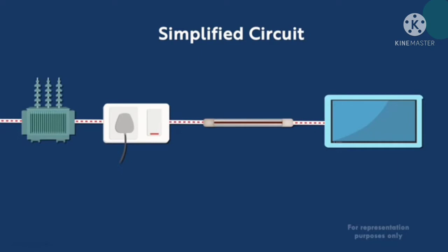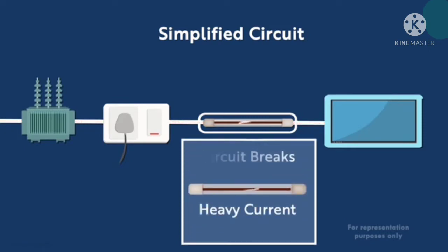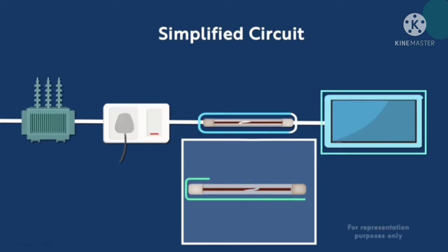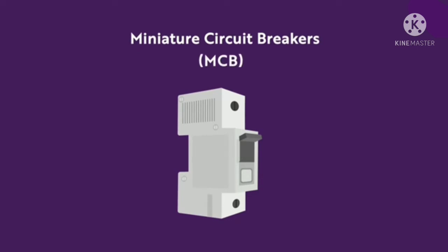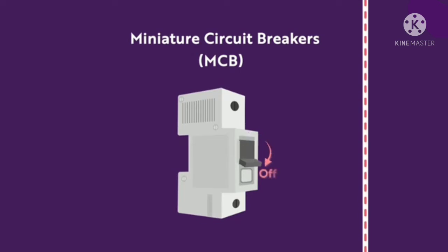See the simplified circuit. Sockets and extensions that are overloaded with appliances are especially at risk of catching fire. All UK plugs are fitted with a fuse, and fuses are available in a range of amperes to suit different current values. So how does a fuse work? A fuse is connected directly into an electrical circuit. If the electric current surges to a dangerous level, the metal in the fuse melts and the circuit is broken, preventing overheating wires in the walls of the house from starting a fire.